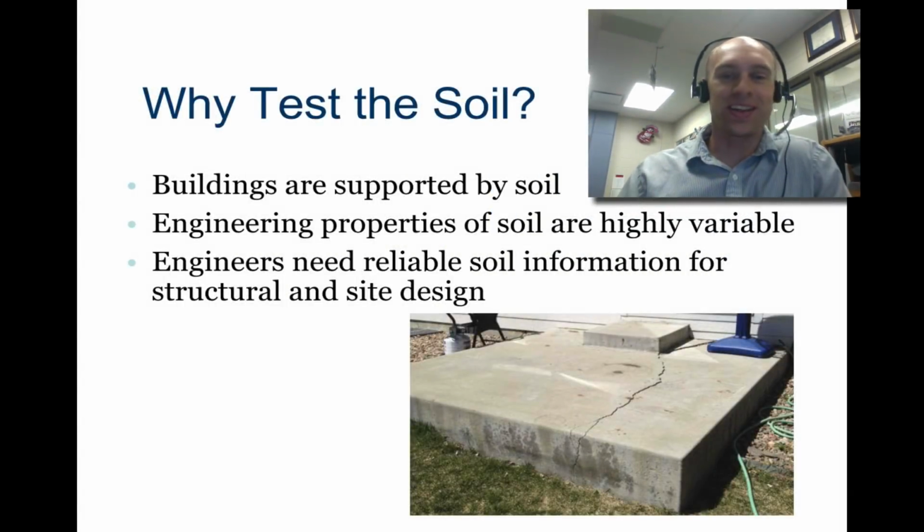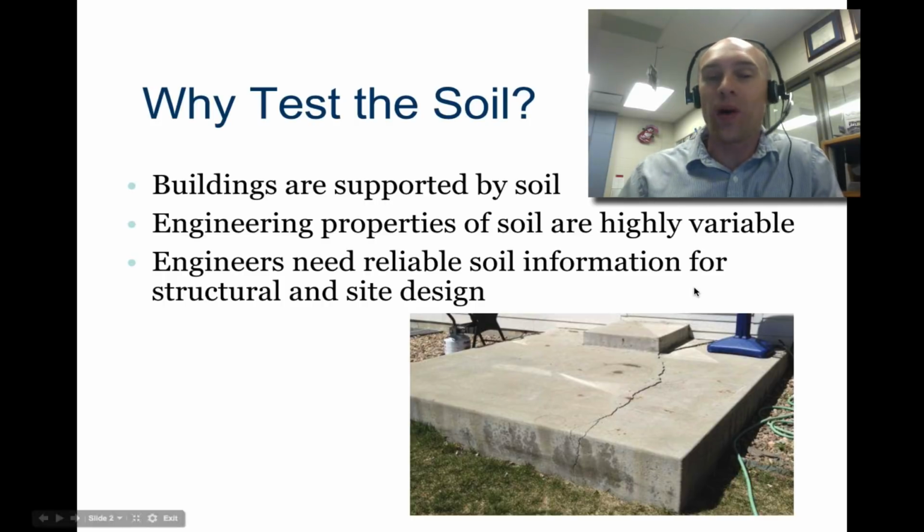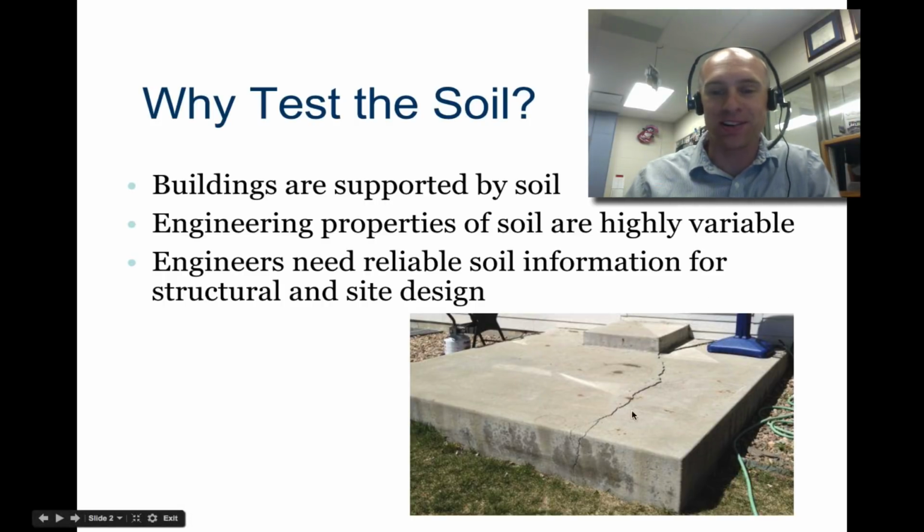Let's look at soils investigations. So we're going to take a look at why you would want to test your soil. This is actually a picture of my old back concrete slab outside the back of my house, and this is why you want to test the soil and make sure that you have a firm foundation. Buildings are supported by soil. Engineering properties of soil are highly variable, and they need reliable soil information for structural and site design.